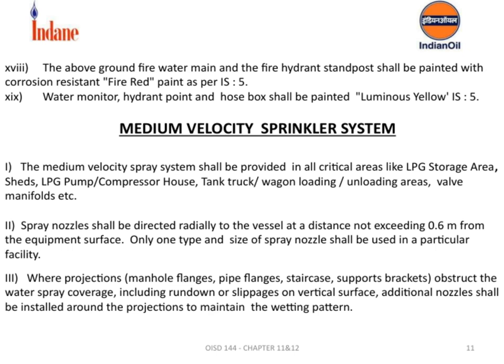Next, in all critical areas, like LPG storage zones, sheds, LPG pump or compressor houses, tank truck or wagon loading and unloading zones, and valve manifolds, we must provide a medium velocity spray system. The purpose here is to ensure rapid and effective fire suppression in these high-risk zones. Additionally, the spray nozzles should be directed radially toward the vessel, and the maximum distance from the equipment surface should not exceed 0.6 meters. It's also important to note that within a single facility, only one type and size of spray nozzle should be used to ensure uniform performance and maintenance simplicity.